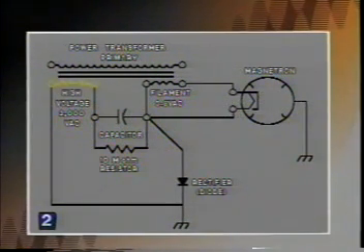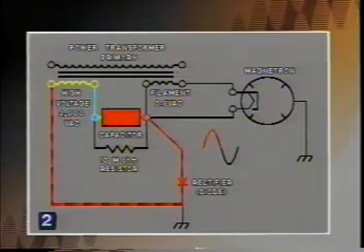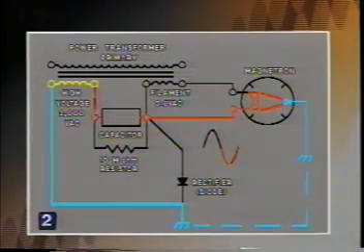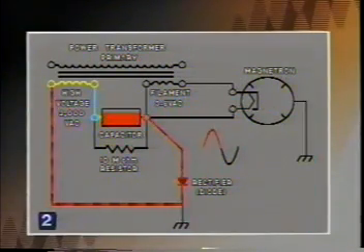The nearly 4,000 volts necessary to activate the magnetron is developed through the use of a voltage doubler circuit containing a diode and a capacitor. Both the positive and negative portions of the sine wave are used in the transformer's secondary winding to provide a total of negative 4,000 volts of direct current to activate the magnetron.